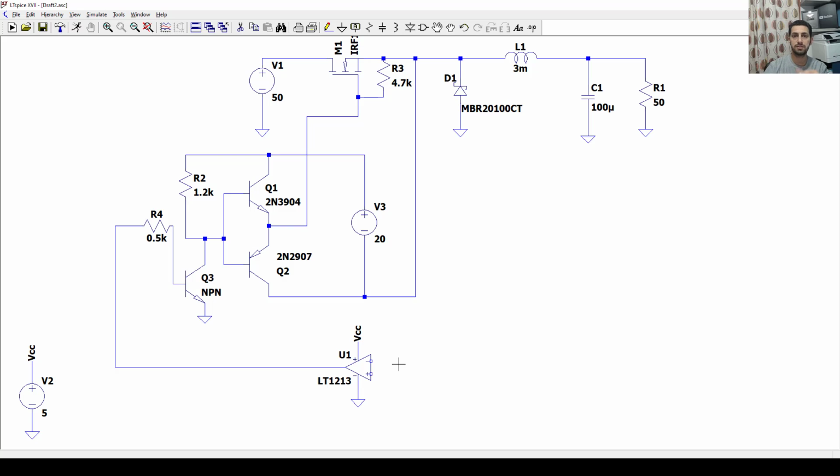Now, I said that PWM generation can be implemented by comparing a triangular wave. A triangular wave has some circuits, but I will not do it by circuits, not to complicate my simulation here. So I will bring here another source like that, and that source is grounded.